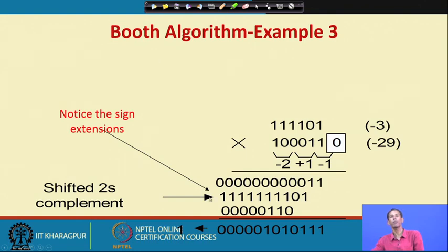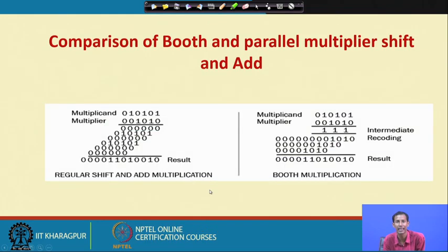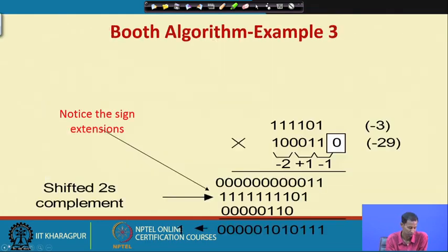Then what is the problem here? Is there any problem? Yes, obviously there is a problem. As I am increasing the sign bit for these particular partial products, that means I am increasing the full adder cells, whenever I use them to add these particular bits using a Wallace tree or any other addition operation.